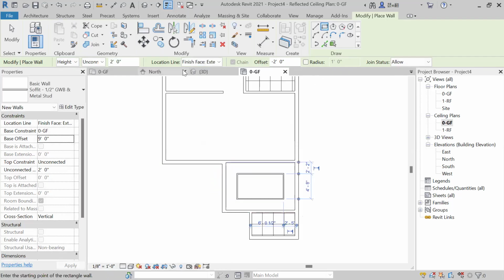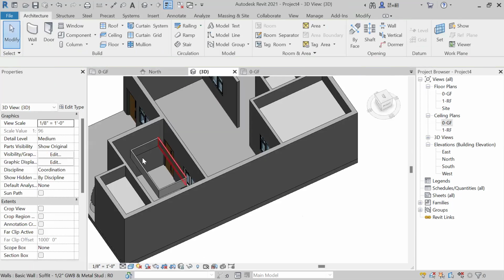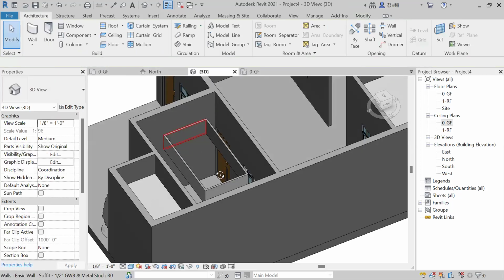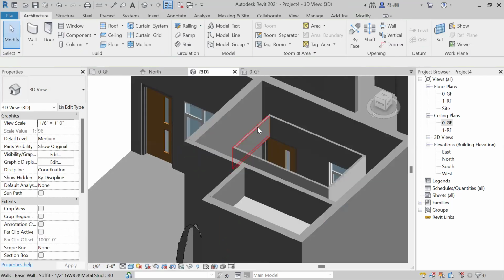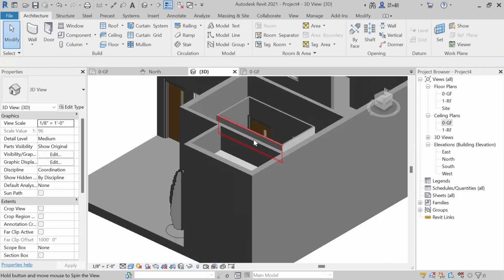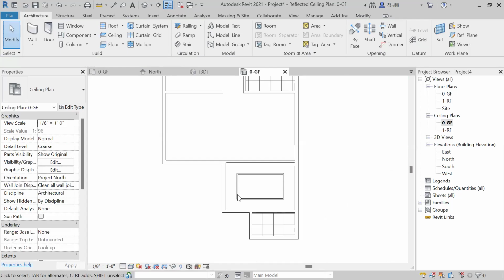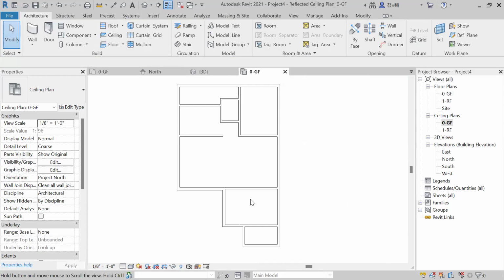And finally, see in 3D view how it will look. Here we have created this step. Total step height is 2 feet. Okay, base level 9 feet and 2 feet height means here how much? Tell me. So see here what I am doing. Just select the base level 10 feet. Okay, 2 feet step I want. Select the base level as 10 feet.